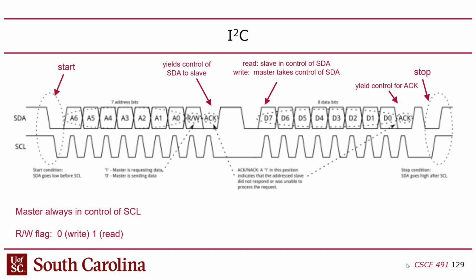Okay, make sense? Okay, I2C doesn't do it that way. It uses a level-sensitive clock, meaning that it's not using the edge of the clock to sample the data, it's using the level. So whenever the clock is high, it samples the data while the clock is high. So what that means hardware-wise is that I2C uses a latch-based system to read the data instead of a flip-flop-based system, right? It is level sensitive.